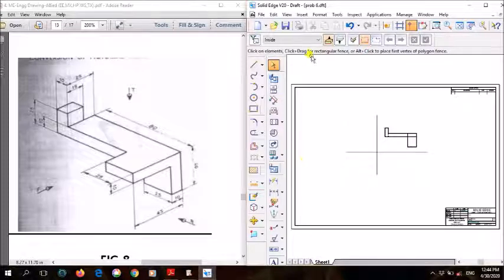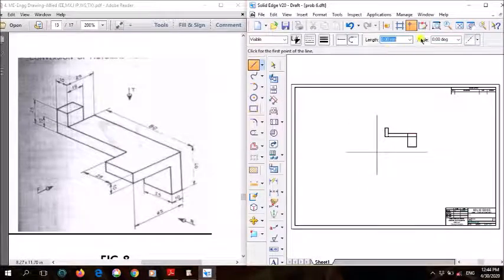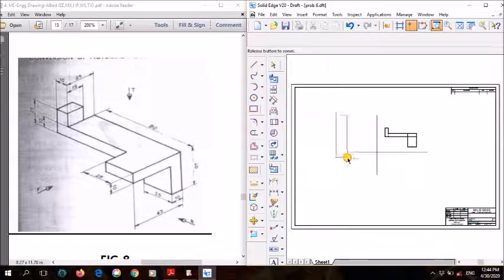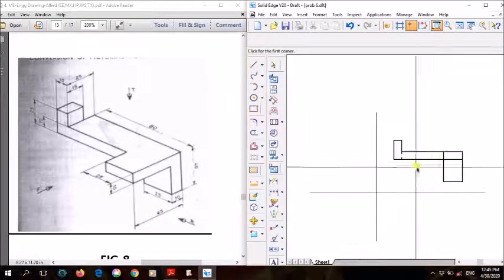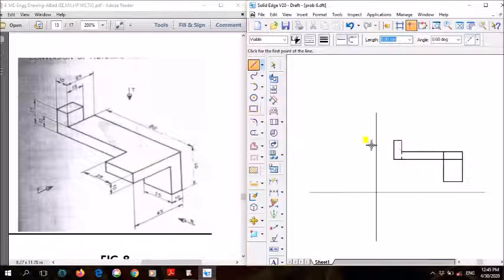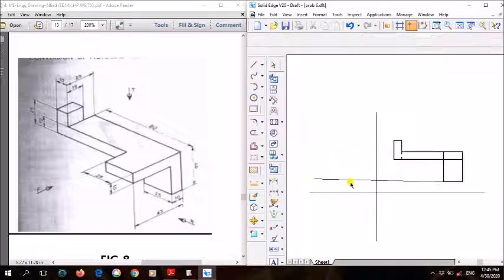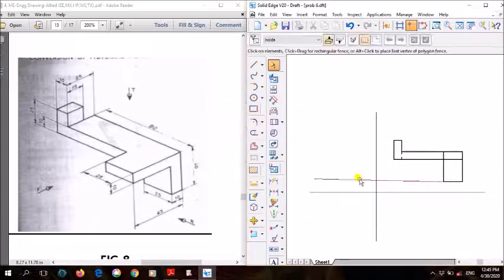So what you can do is, again the same way, I'll just zoom it. We'll project this projection line from all the corners, and automatically we'll get the right view. So here you project this corner from here, a straight line, using a thin line.